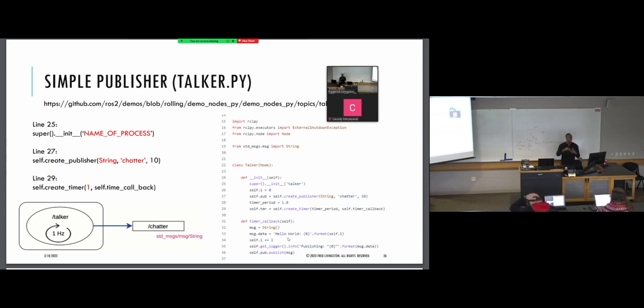So this is a loop. All the ROS code is running in some kind of loop, and the loop is running at that 1 hertz. And so we use timers a lot to make something happen over and over again. That timer is always going to get called back again. It's pretty accurate: if you say 250 hertz, it pretty much hits that 250 hertz. So I wouldn't go too crazy with speed, but it can handle pretty high speeds as well.